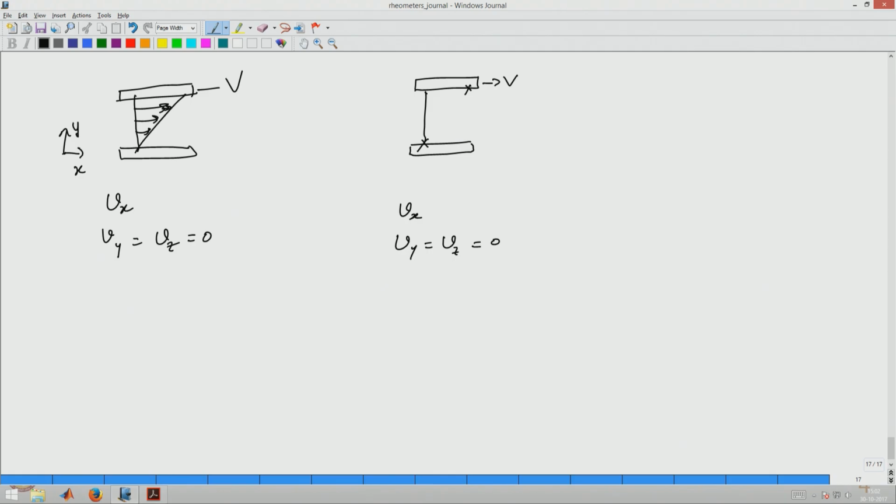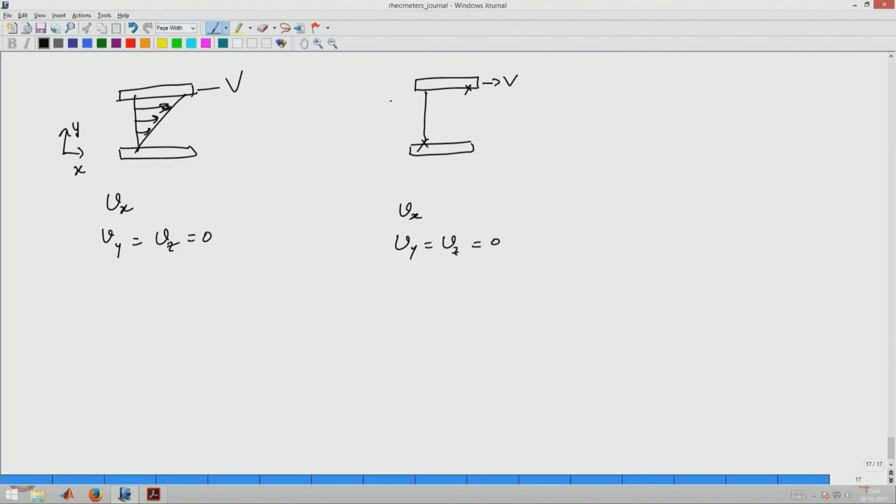If there is a suspension, the velocity increase will not be regular. Yes, that is one aspect that we always have to worry about. Whenever we talk of suspension, there is always heterogeneity in the material. By definition, the material is heterogeneous. So generally in rheometry we say that the plate separation should be at least 10 times the particle size.